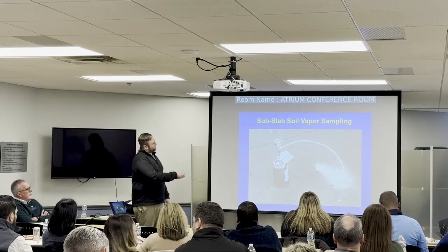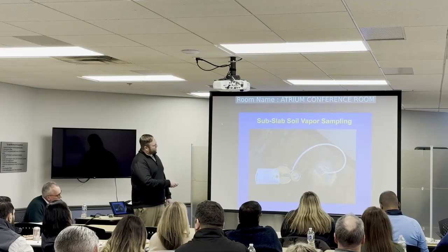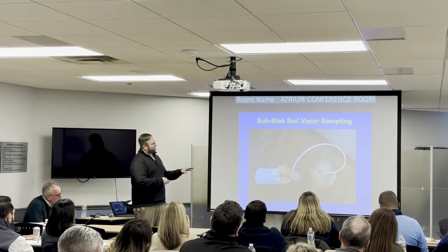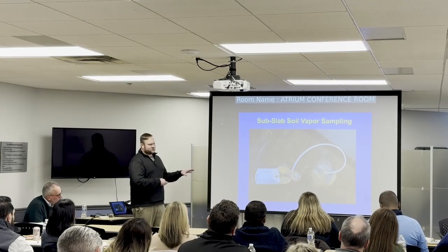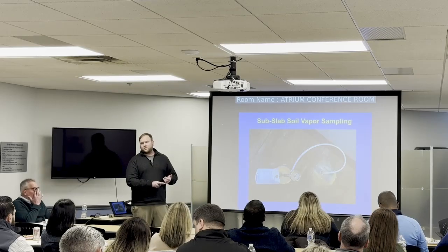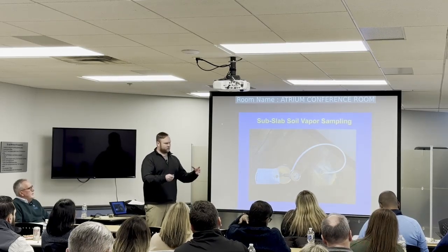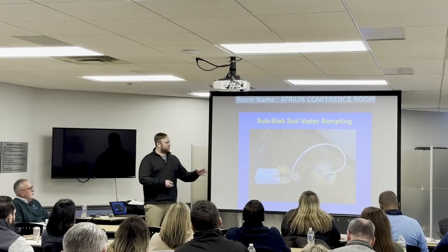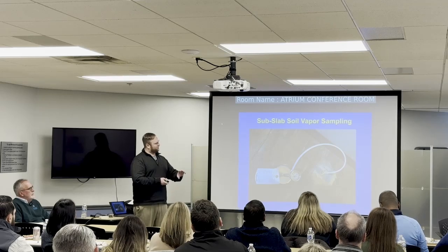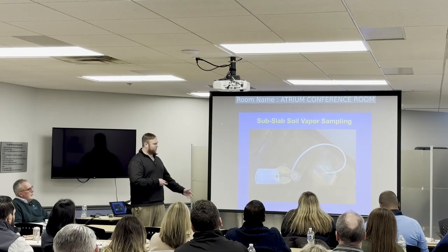So this is exactly what is being sampled there. Here's another example of it. In this one, I've drilled through the floor in a hotel. It's not very pretty. The nice thing about collecting sub-slab vapor samples is you can get into a lot of areas you usually can't access with a rig. You don't have to drive a truck into somebody's building. You're not creating soil spoils. Once you're done, we remove this pin, patch it up. It's sealed at the slab, and with the exception of maybe a little discoloration, you'd never know we were there.